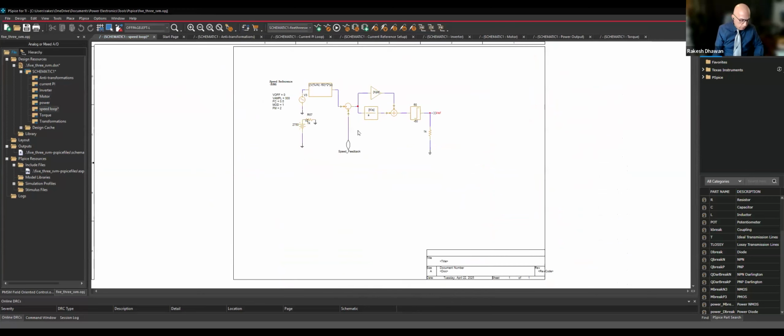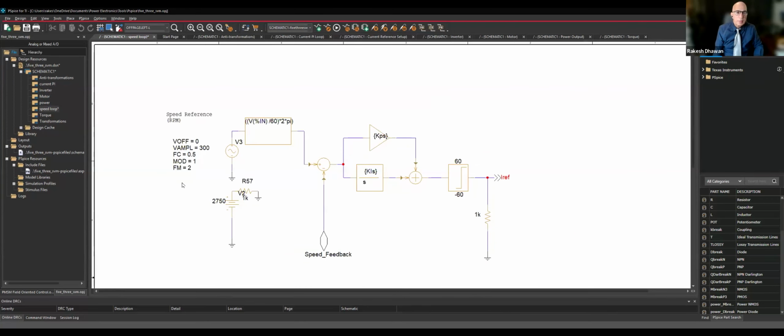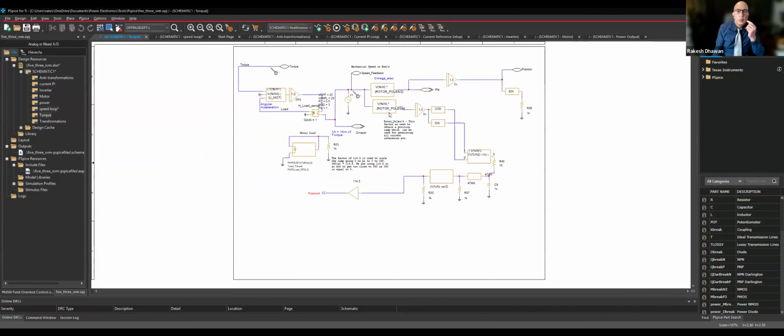You can also implement a speed loop on top of this, where you can convert the output of your speed loop into a current reference, right? So without field weakening, under your base torque and speed curve, you could run this experiment. You can also play with the dynamic response of your speed and how the motor responds to your speed command.